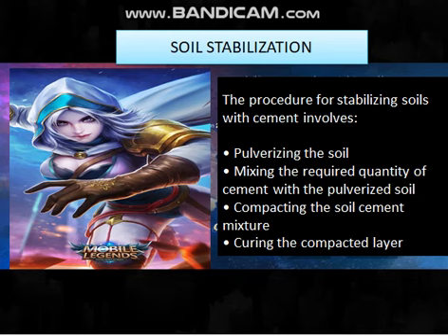The third one is compacting the soil cement mixture. It is essential that compaction of the mixture be carried out before the mixture begins to set. The soil cement mixture is initially compacted with sheep foot rollers or pneumatic tired rollers when the soil, for example, is very sandy, so it cannot be effectively compacted with a sheep foot roller.